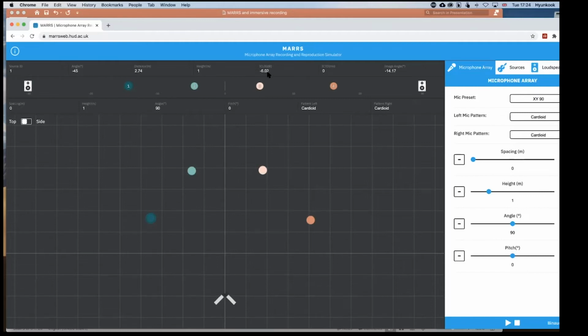So 6 dB is never going to be enough for a fully wide stereo image. You need to place the microphone very close to the ensemble. Then you get the necessary 17 dB difference. So this tool visualizes this, and then I'll play the sound now. Hopefully you'll all be able to hear the binaural audio.